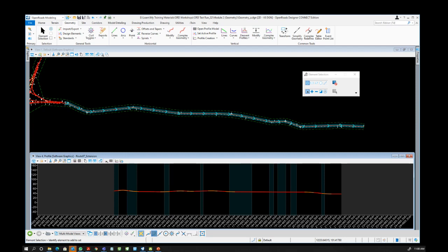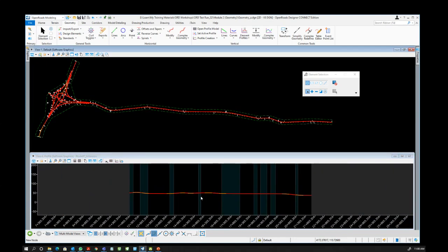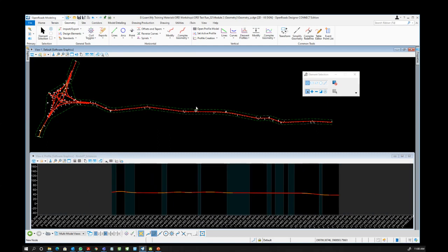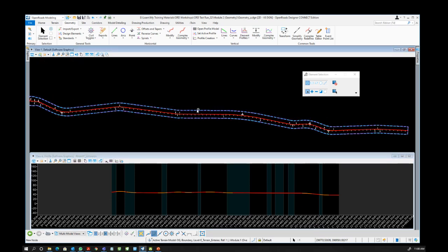Okay, sorry. Let me just turn off that. Okay, now where is my surface? How come it only shows me my profile? So the surface you can see relative to your profile by activating. Remember the activate terrain. So select your terrain. Let the context menu pop out. Click the icon.